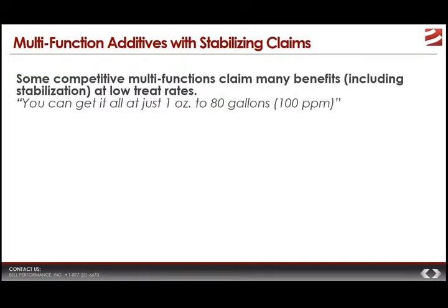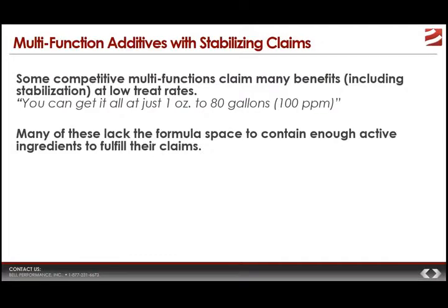Now, a quick word about multifunction stabilizers. There are a lot. Stability is one of those things that when somebody's formulating or bringing a multifunction additive out in the marketplace, they will always claim that it has stabilizer in it. Now, the thing that you need to watch out for here is that if you have something that claims to do a bunch of different things, you need to know, if it's got a really, really low treat rate, is it going to have a high enough treat rate to actually deliver enough active ingredients to do everything that it claims to do? A lot of these simply lack the formula space.